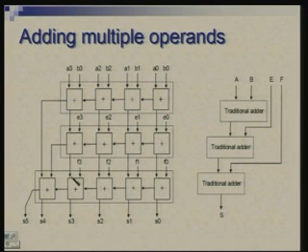So, here what we can do is since we have to go to the next stage, we have to wait for signals to propagate vertically. We can take advantage of that and prevent propagation of carry to just the left neighbor of one adder cell. So, logically it is equivalent that let us say if this carry instead of going from here to here, suppose it was to be sent to this one,